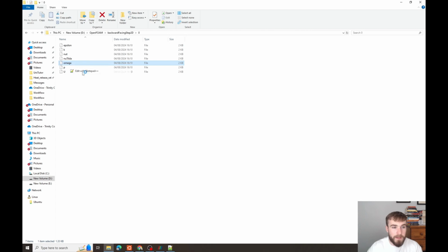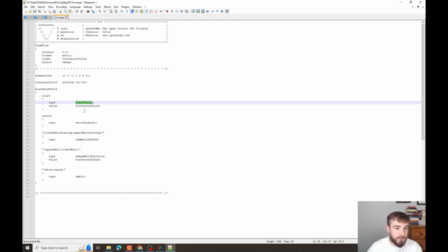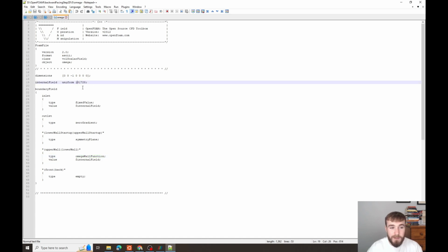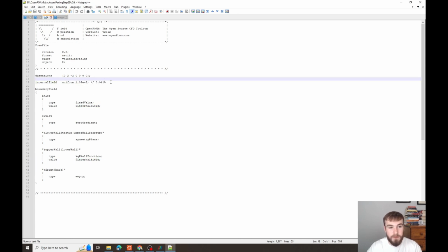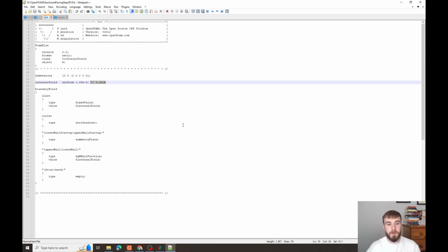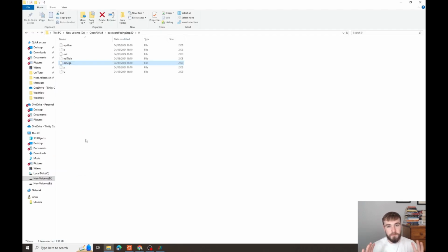Very similar stuff then with omega. Almost exactly the same: fixed value at the inlet, 0 gradient, and we're using an omega wall function to compute that turbulent value of omega there. Then uniform within the field, I believe this uniform value would have been calculated from the turbulence intensity that I talked about. So you can relate K and omega. For a specified turbulence intensity, you can calculate what K and omega are just through simple hand calculations. So I won't go through that because it's very simple. It's like a 3-letter equation. So that's the boundary conditions fully defined for the inlet and the outlet.